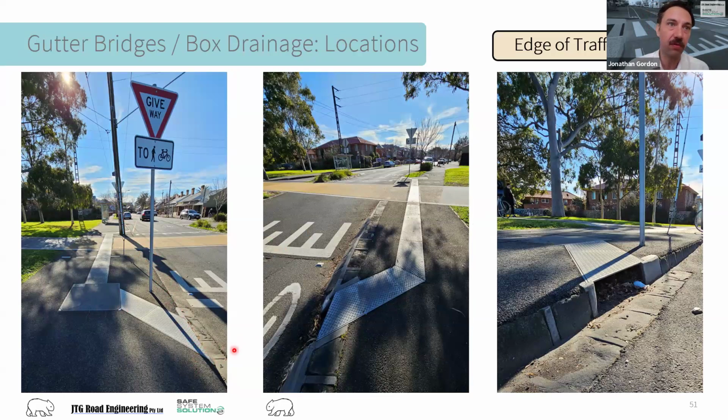And the intent here is that water flows in. This is still a continuous curb to curb flow system, and the intent is that water inlets comes through and outlets at the other end. You can see here, though, over here, and I've done it on both sides of the road, sorry, that's why I've got the image in the middle here. But over here, you can see this building up with debris, and that probably touches on the key issue for these systems and why they present challenges for us.